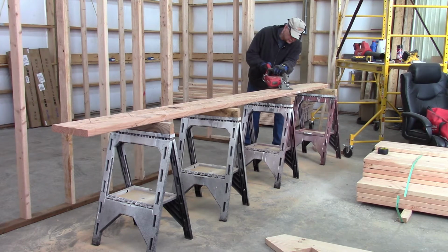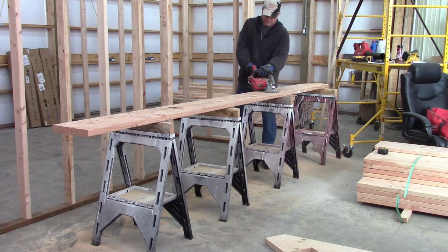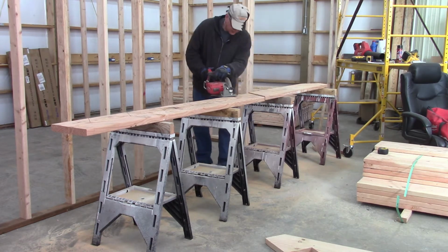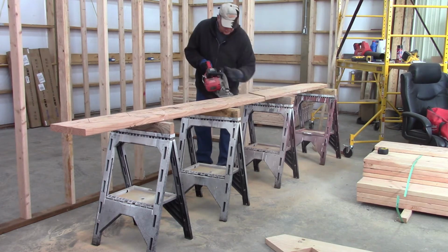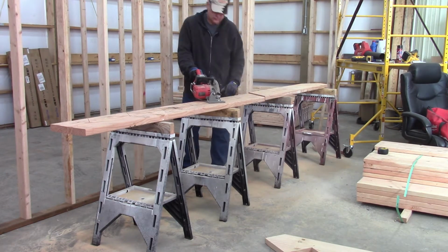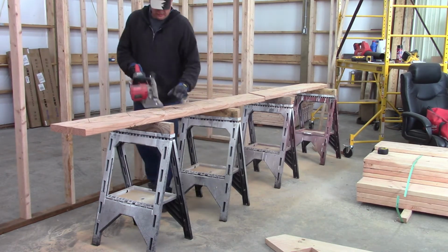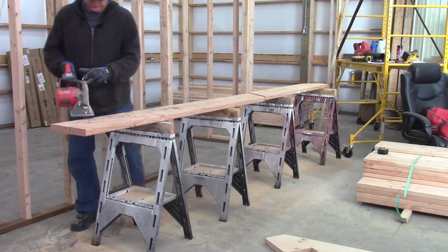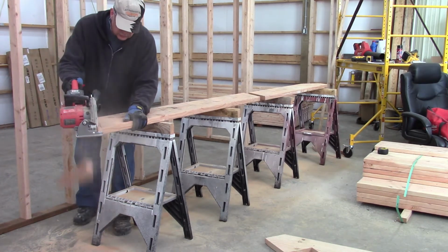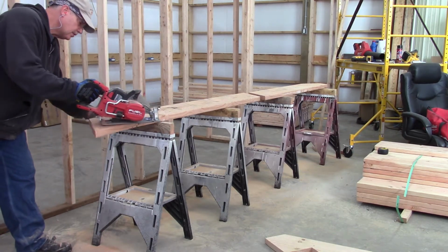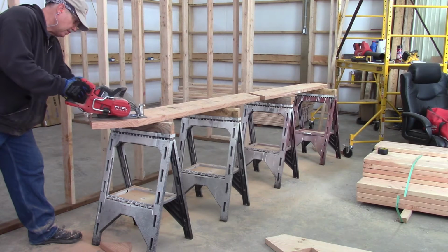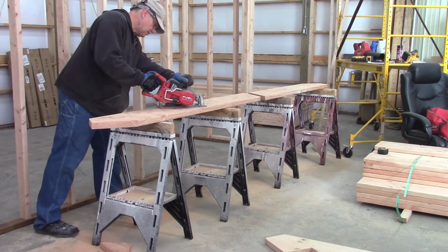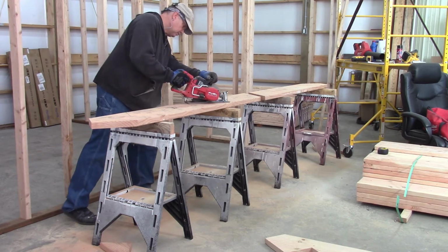I cut all of the marks along the lines, and then I go back with a jigsaw and finish the corners inside the cuts, so I get a nice clean cutout. Now right there you noticed I cut the stringer ahead of time in half, or not quite, actually less than half, and that's where I determined I want to have the platform. So this way it comes out even, and then I will use these as the pattern to draw all the other ones. Or actually that's what I already did, because you can see the one on the floor there.